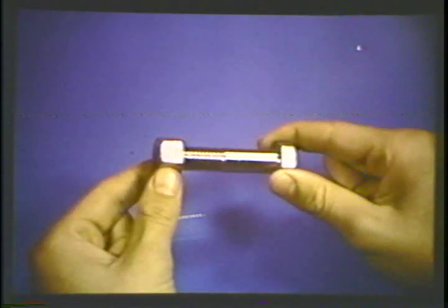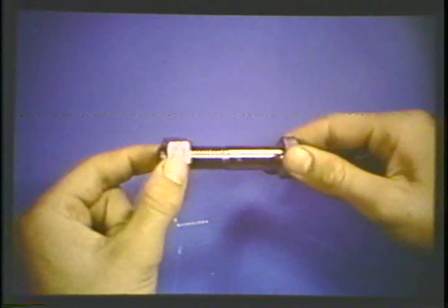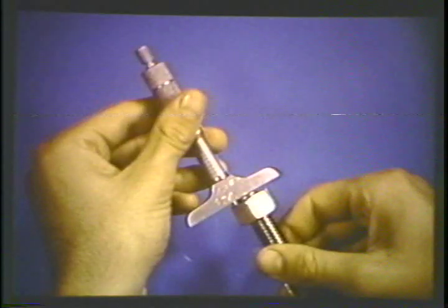Screw a nut on a bolt until the end of the bolt is flush with the outside edge of the nut. Next, turn the nut exactly 1 revolution. Now measure the amount of thread sticking out. The amount you have just measured is called the lead, which is the distance the thread advances along the axis of the bolt. You have learned another thread term.